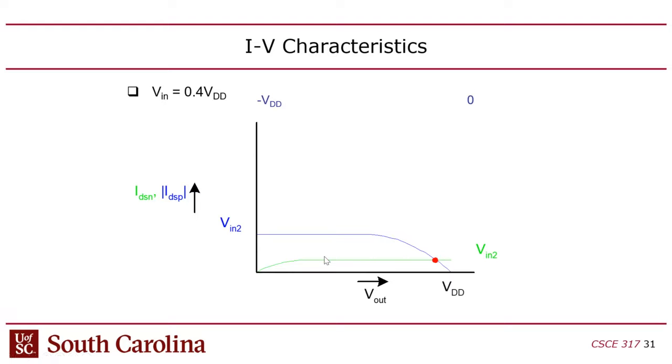So they're both on, but they're just both on to different degrees, because of that voltage, 0.4 VDD. We're right in the middle, right? Instead of giving it a 0 or 1, you're basically giving the gate a half. Essentially, both transistors are on, and you can see that the PMOS is basically in saturation mode for most of that, as is the nMOS actually. But the nMOS is in linear mode over here, and the PMOS is in linear mode over here.